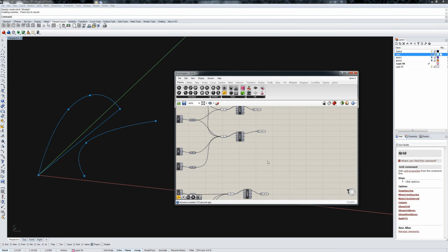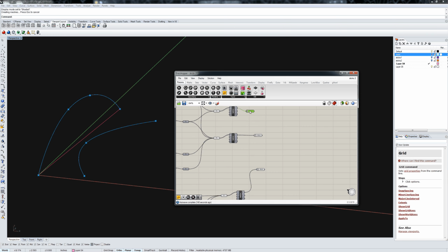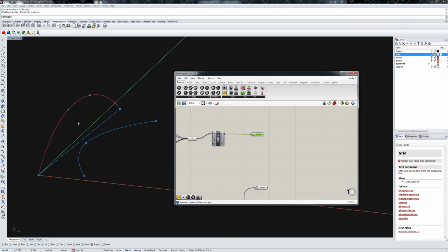So one more quick example, and this was something I did at the end of class. I asked the question, what if you were modeling not with sticks and wire, but like trace and wire or latex and fabric, and wanted to create surfaces in between your wires? So here I have the same model from the previous tutorial, and I'm going to show you how to create a surface between wire 1 and wire 3.